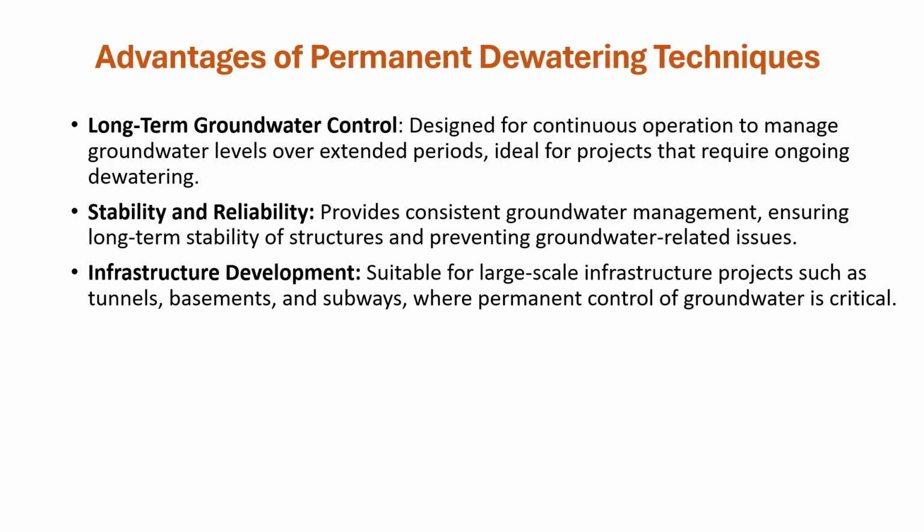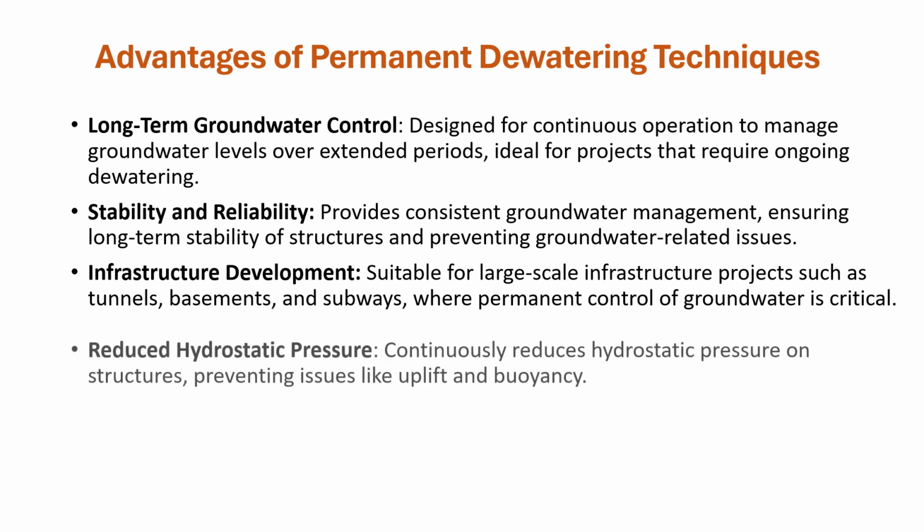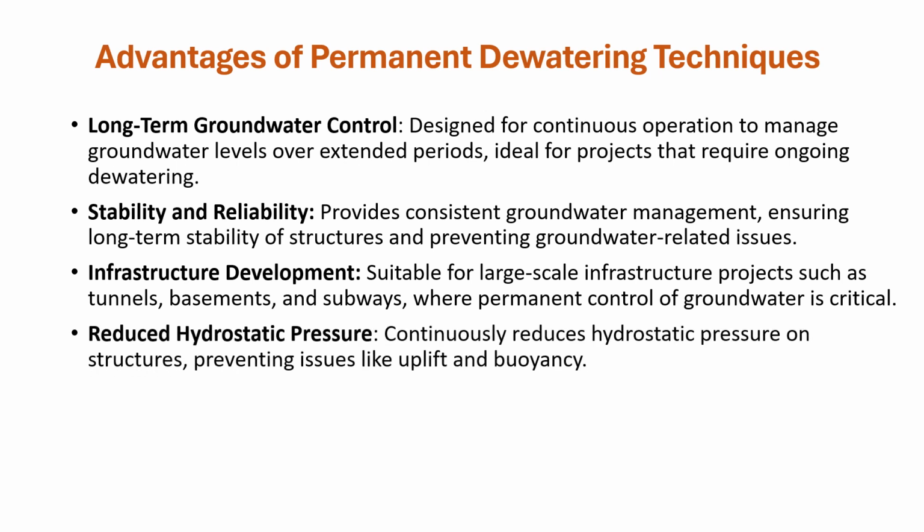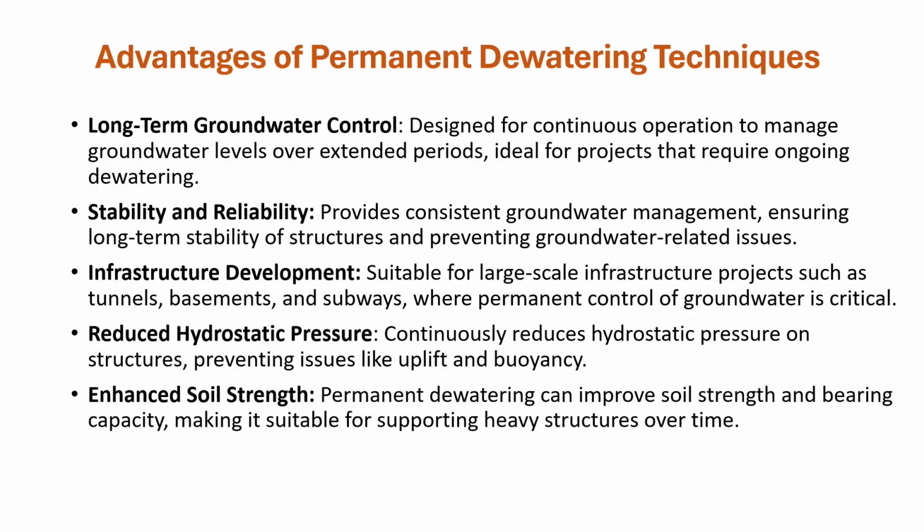Such dewatering systems are suitable for large-scale infrastructure projects such as tunnels, basements, and subways. And they are able to reduce the hydrostatic pressure on the structure, thus preventing uplift or buoyancy. As we know, when we remove the water from a certain soil, and we are doing this in a continuous manner here, thus the soil strength and the bearing capacity will be improved.